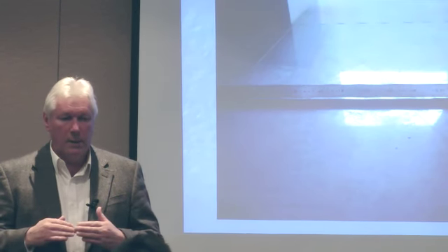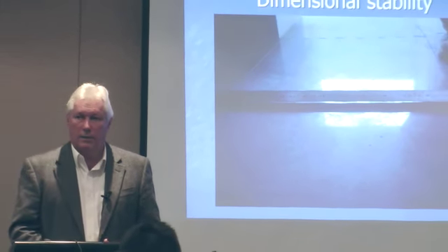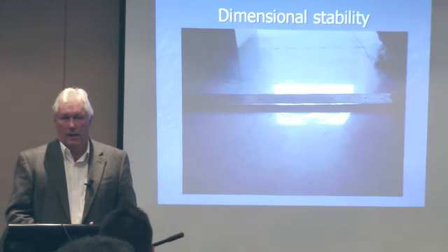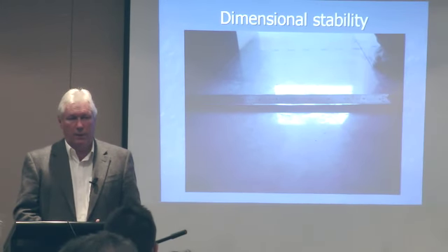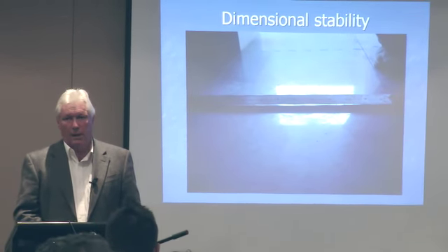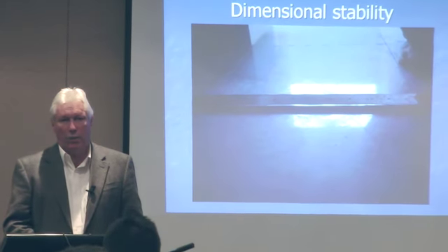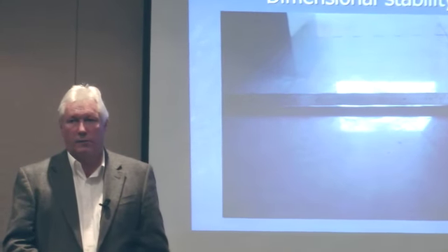That means that there's a little bit of movement, we're usually only talking a millimetre or so. The curvature can be quite radical and happen within an hour to 4 hours of being wet, and it can then sometimes dry out within the next day or so and drop right back down. So you might have had 3 millimetres of curl and you only end up with a 0.5 millimetre of curl, but it's broken the bond, and the tile, when it's loaded, can move, and then the grout joints crack and you're in trouble.